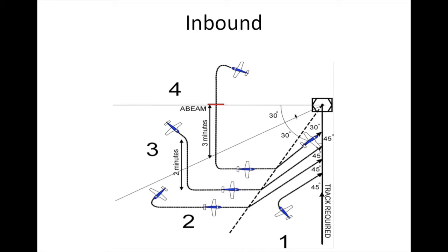As you can see in this picture, let's say you are heading in any direction. It doesn't matter what direction you're on, all that matters is if you're in a specific sector. See here, let's say I've been instructed when I'm here, the aircraft is in section 2, and you're going away from the VOR. You've been instructed to intercept radial 180 inbound. First thing, I found out now I'm between 30 and 60, so I'm going to fly perpendicular to it first, that is 090, until I'm 30 degrees away from it. Boom, I turn 45 degrees left, and then at that point I'm flying in the direction 045, and then intercept the radial 180 inbound, and then fly straight ahead towards the VOR.